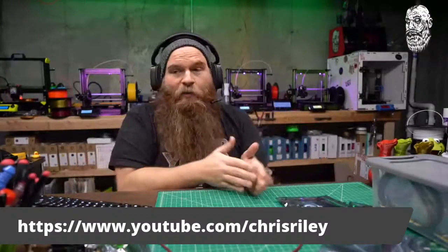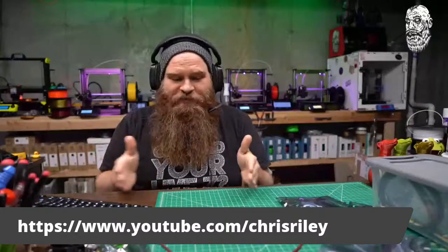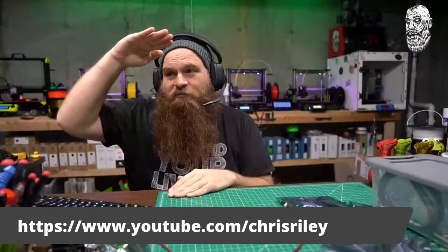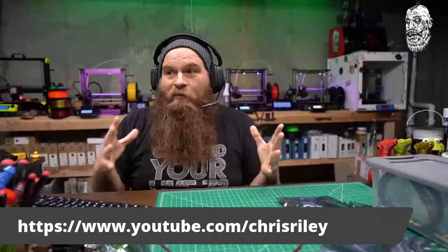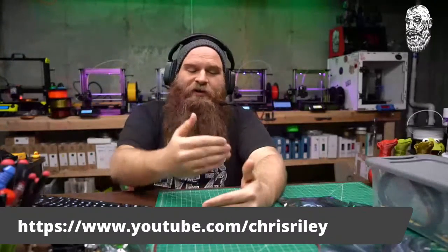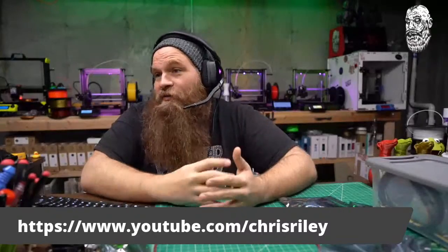The next step, after you figure out what hardware you have, is to know what sizes everything is. If you don't know your printer's actual physical movement space, this is going to get weird. A Prusa is 250 by 210 by 210. My Artillery over here is 310 by 310 by 400. So you need to know what your working space is. That's a setting you have to change. So get all of your stuff and write it all out. Write down what boards you have, what drivers you have, what other components you want to add, and also your physical print space.